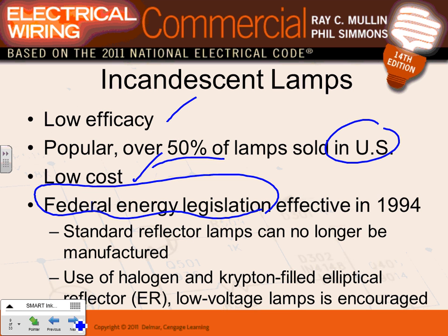There are problems if your whole house is all CFL lighting, with harmonics and stuff like that. They're working on the harmonic issues. Supposedly the ballast that comes with these compact fluorescents has to be maintained within, I think, 5% total harmonic distortion. The fluorescents have to be maintained within, I think, 10%. If you maintain them within 10%, the overall effective harmonic is not as big. So anyway, we're not using them, guys.